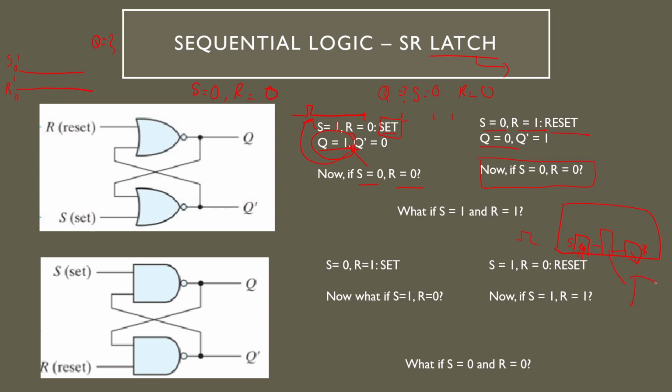to some central CCTV system, and this central CCTV system is constantly reading the value of Q. It sees the value of Q become 1, and now it registers the room as occupied. Similarly, now you could be in this room, and you could leave at any time. That would set R back to 0, that would set this screen to vacant. But what's important is the person looking at the screen, the security guard, doesn't need to be there when you walk into this room to see that the room is occupied. The room remembers its state.